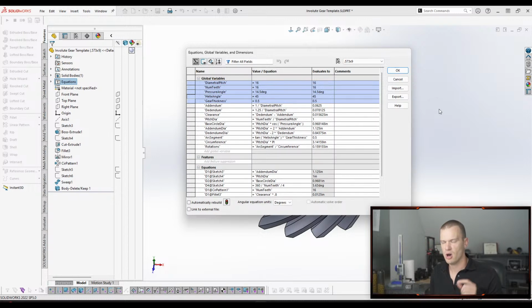If you know that the geometry needs to be correct and you can't get it directly from the manufacturer, I would just build one of these models yourself and build it so that it's parametric and you can just punch stuff in. And what I would do is I would punch in a gear, and then you can either save it as a configuration if you wanted to start building a library of commonly used gears that you have.